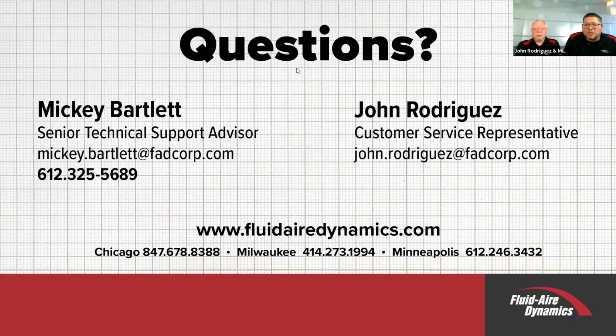What ambient temperature do you recommend a compressor room to be? As cool as you can, but not freezing. Like 60 degrees, but you're not going to get a 60. If you can keep your compressor room at the outside temperature, that's good. And when you build a compressor room in a new plant, outside wall, outside wall, outside wall, because if you don't have an outside wall, you can't ventilate. It's tough to go through the roof. The outside wall is very important. So the end result is the compressor room should be as cool as possible.